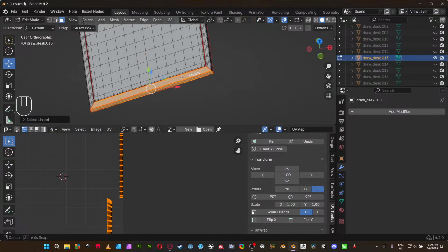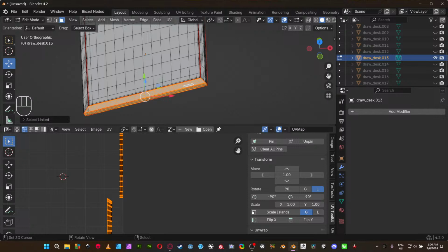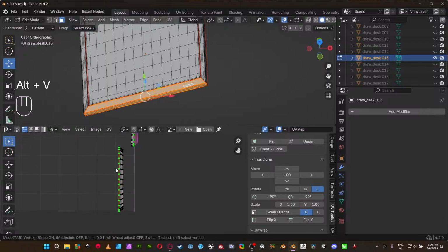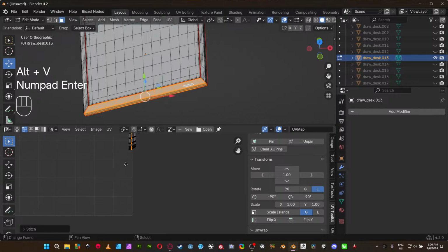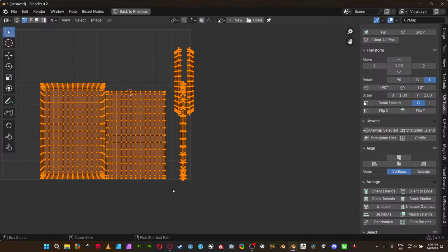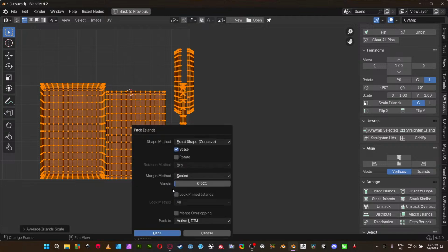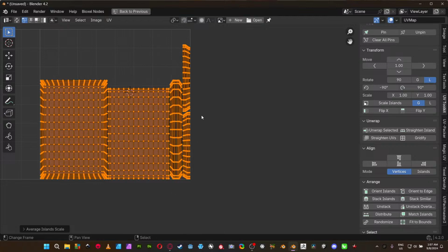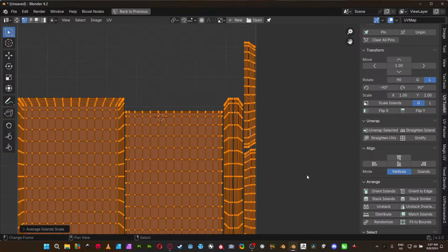It's because, as you can see here, we have this trapezium, the biggest large piece that is connected with the other guy. So I go directly here, Alt B, and then click it, then select everything and see what we already have in here. So Control A, Control P, let's pack, and then we have fewer islands to deal with.